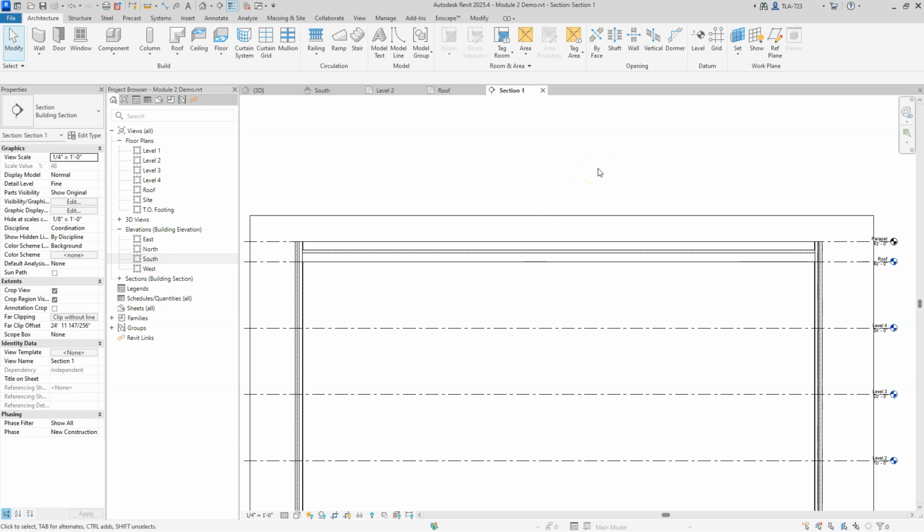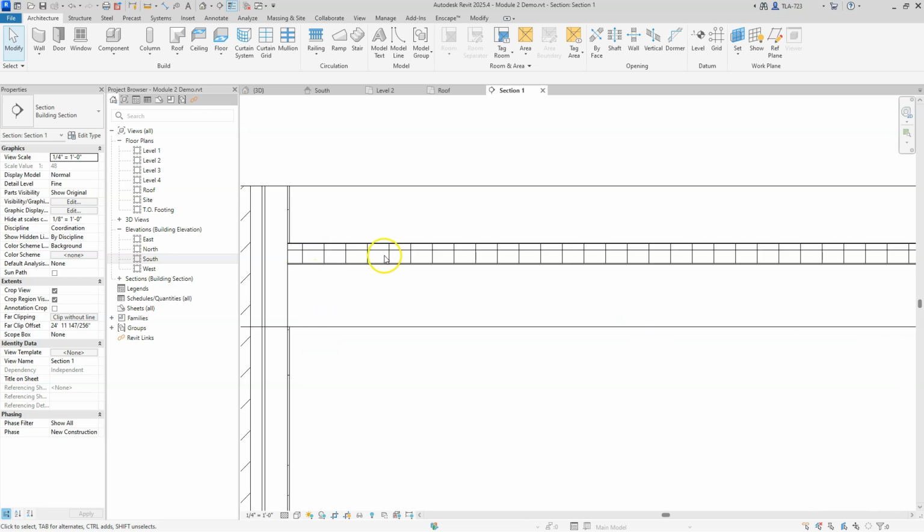We'd probably end up with progressive structural collapse. The goal here, as with any roof, is to be able to stop water and shed that water off of it. So how do we accomplish that with a flat roof? Well, we actually never really have flat roofs. There's always going to be at least a minimum slope, and code tells us that the minimum slope for any roof is 1/4 inch per foot. So how do we accomplish that? The trick is to slope the insulation.